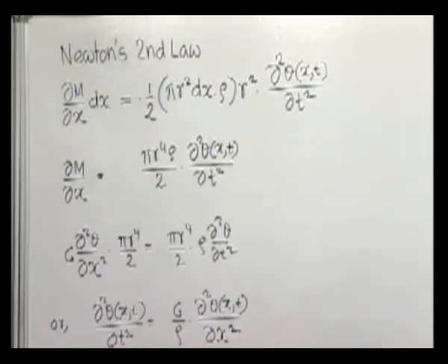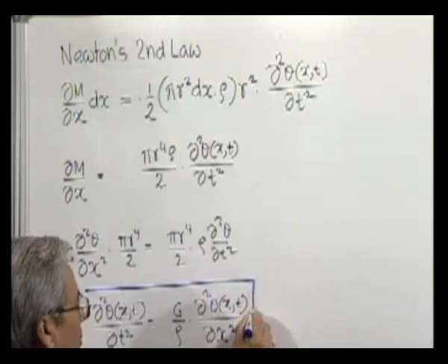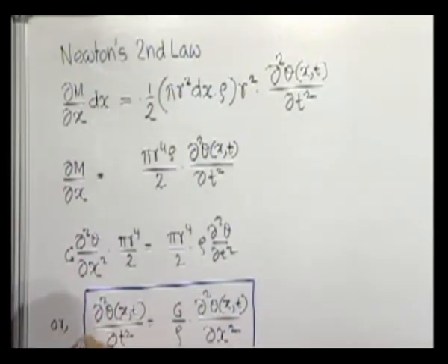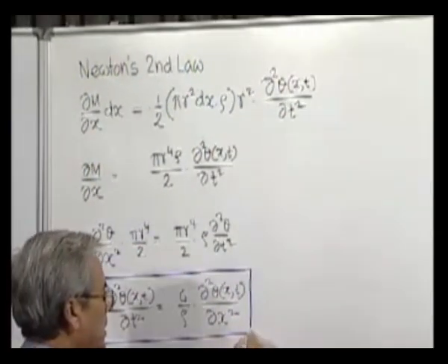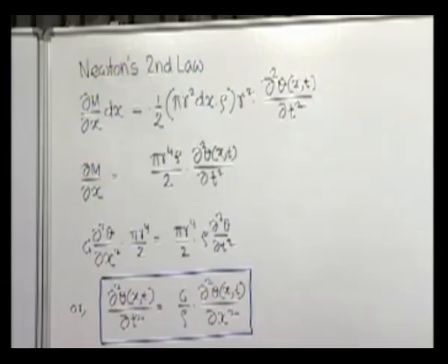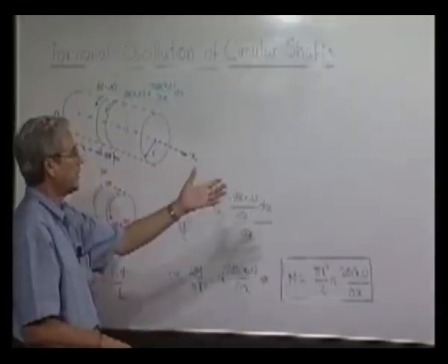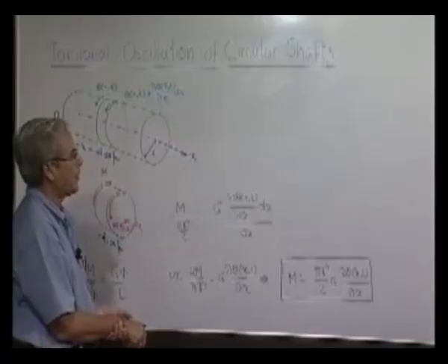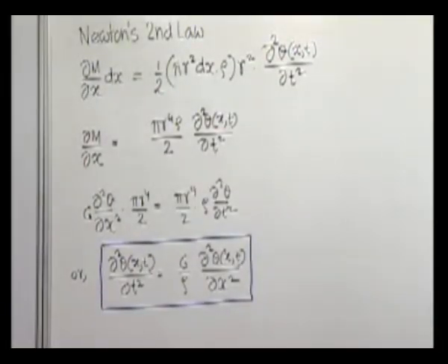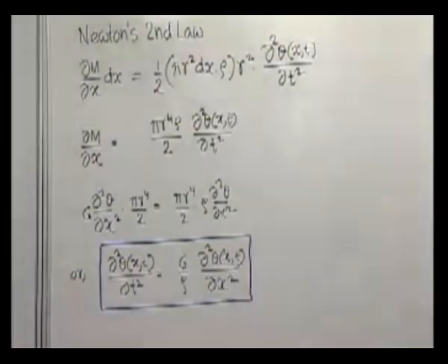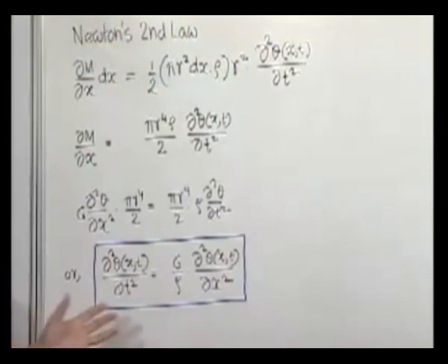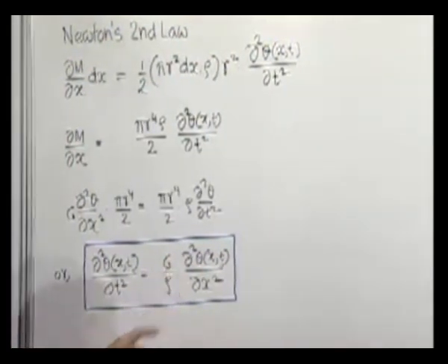an equation which is identical in form with the equation of motion for longitudinal oscillation of a bar. This is the equation of motion, that is the relationship between the angular rotation, time, material properties, location, and so on. If you remember the previous one, in case of longitudinal oscillation it was exactly the same, only there it was E by rho.